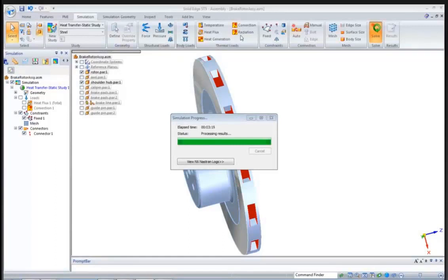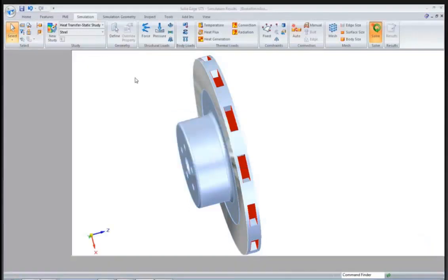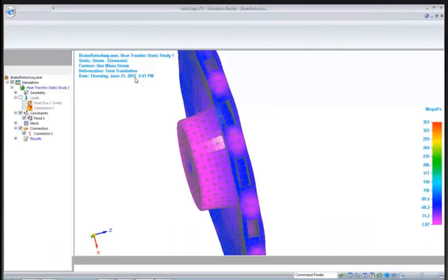Now, the last form is radiation. With radiation, you've all stood out there in the sun. It's just electromagnetic waves carrying photons, so you don't need a medium for them to transfer through. And you've got the Stefan-Boltzmann equation, which says the surface temperature to the fourth power times the Stefan-Boltzmann constant, and then you multiply that by emissivity to get the heat flux. The emissivity is another material property that you look at, and an ideal radiator has a value of 1. It radiates perfectly, it's a value of 1. So everything you're going to do is going to be below 1.